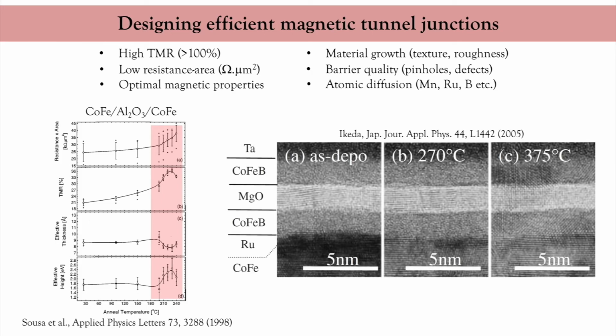In the case of Iron-MgO, the objective is to obtain a nicely crystalline tunneling barrier. To do so, experts use amorphous cobalt-iron-boron magnetic electrodes and anneal up to 400 degrees Celsius. You see that at 250 degrees, the interfaces are improved, which means that the oxygen that had diffused into the ferromagnetic electrodes is now back in the MgO.